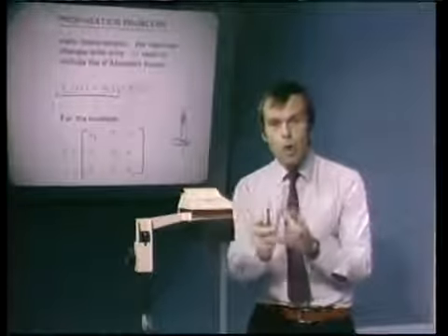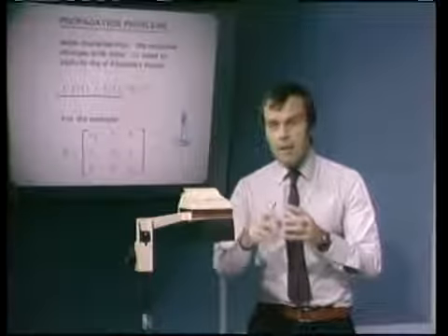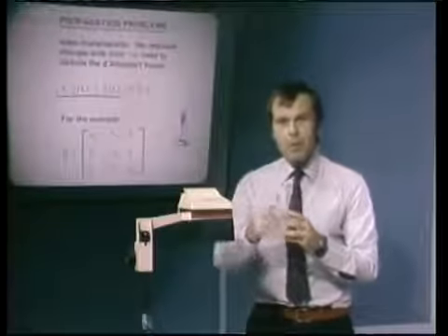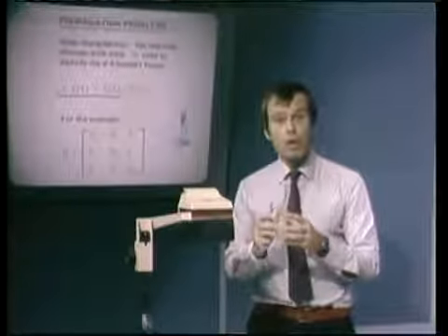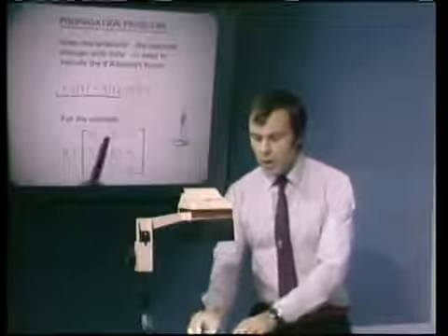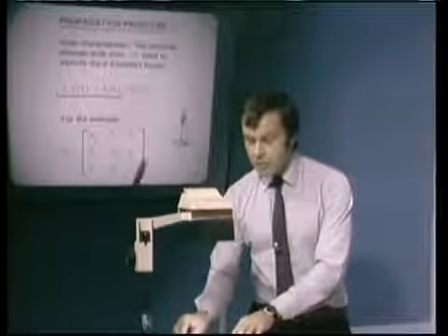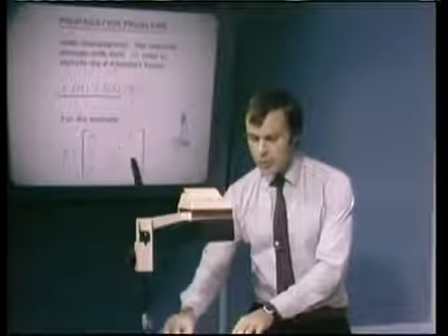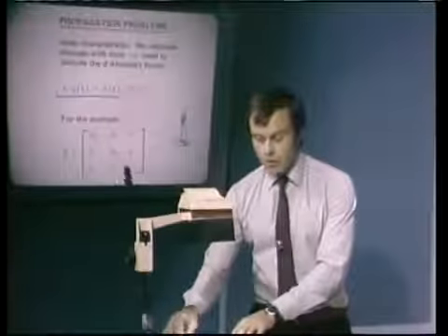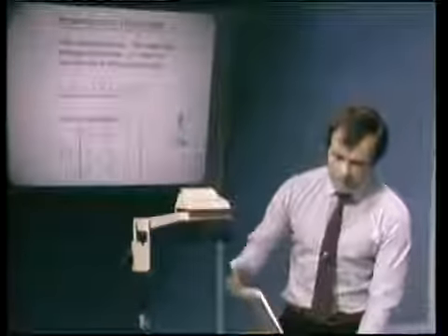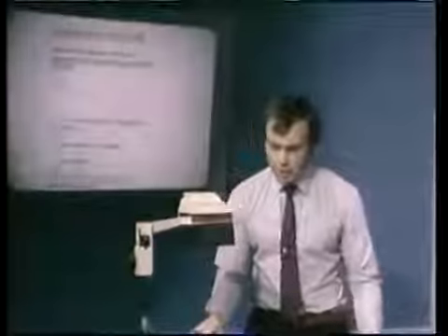When we talk later on about actual finite elements, we will be talking about similar mass matrices where we will simply take the total volume of an element and lump that volume of the element to its nodes. We will also talk about consistent mass matrices where this mass matrix is a little bit more complicated. In other words, some of these off-diagonal elements are not 0.